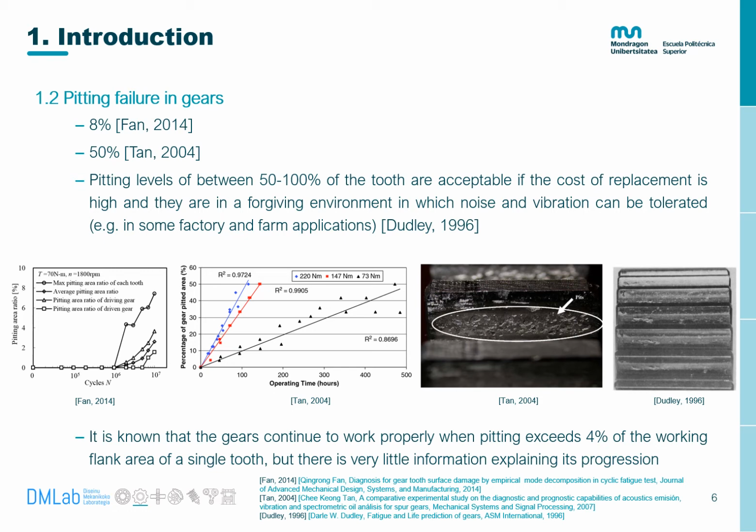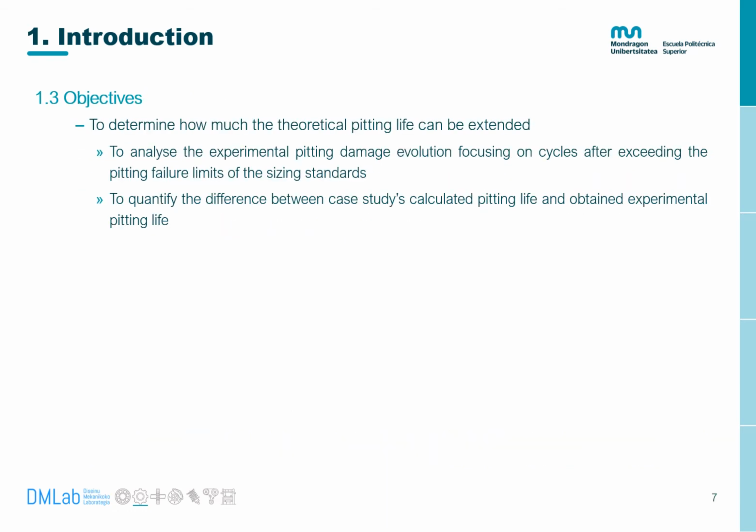To conclude, it is known that the gears continue to work properly when pitting exceeds 4% of the working flank area of a single tooth, but there is very little information explaining its progression, which is essential in order to extend gear life.